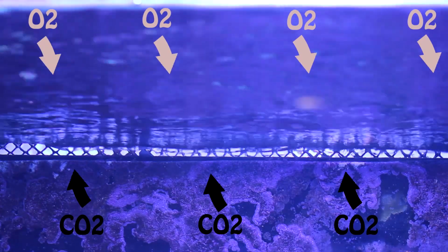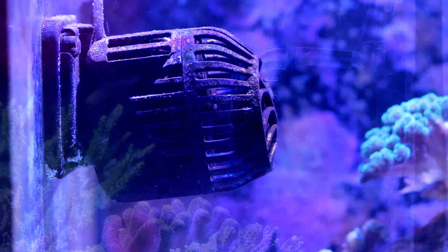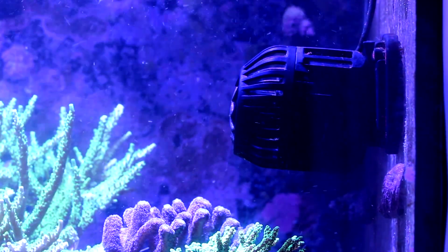CO2 affects the pH values, so if you are struggling with low pH, that means that there is too much CO2 in the water. Not enough flow and water movement may be the cause here.